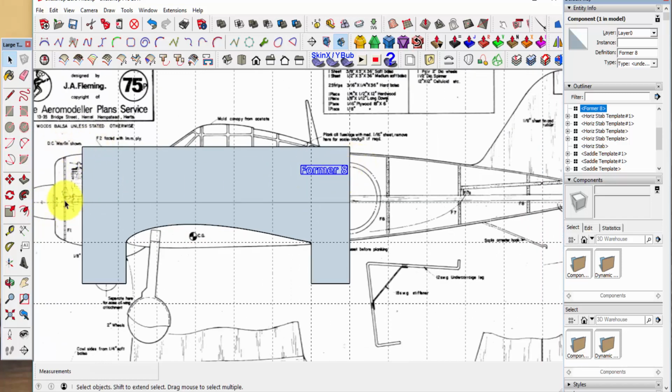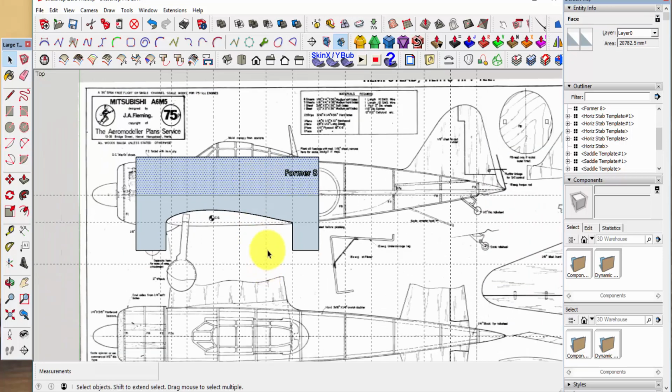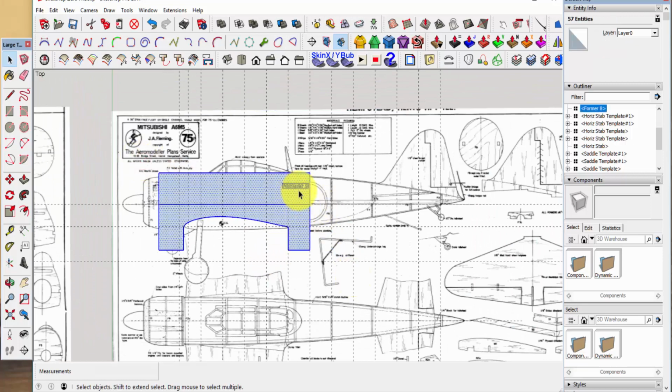Now there's not going to be one forward. What we're going to do when we tape this to the aircraft is we'll cut a tiny hole here so that we can see this line on the former and align it with our ever important datum line. So now we know former number 8, the datum line, and then we'll cut out a little peekaboo in the template up here. And again, you're going to need 2 of these. So we'll take this now. I really don't want that to be a component, they drop lettering in as components. I just want it to stick right there to our template.